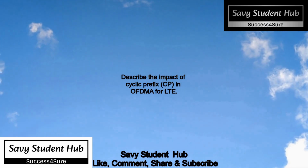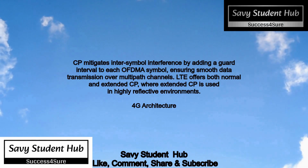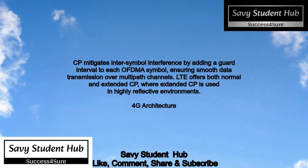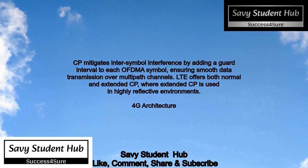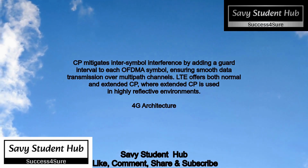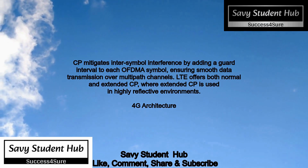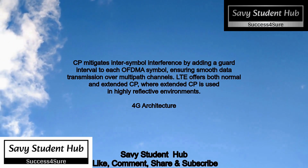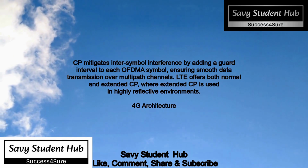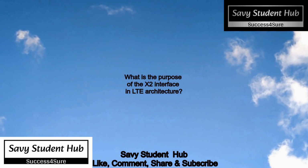CP mitigates intersymbol interference by adding a guard interval to each OFDMA symbol, ensuring smooth data transmission over multipath channels. LTE offers both normal and extended CP, where extended CP is used in highly reflective environments. What is the purpose of the X2 interface in LTE architecture?